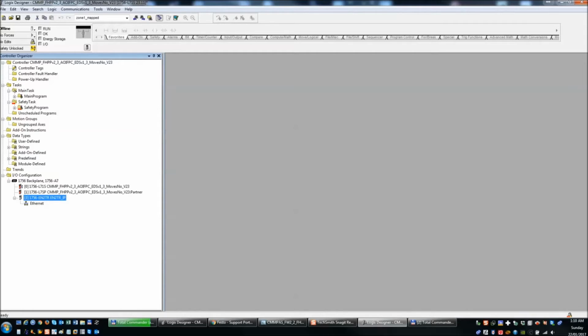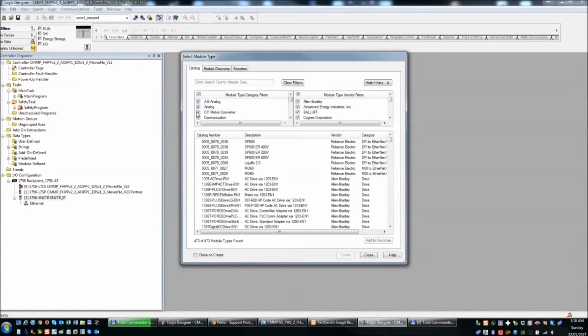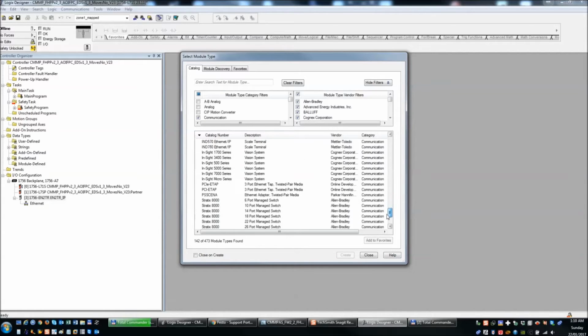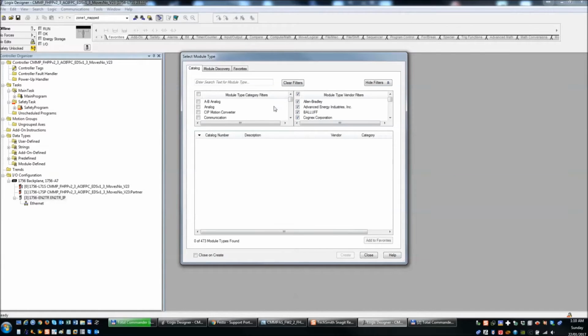The next step is to actually add the drive. Now, right-click on the Ethernet card because that's where we're adding it, and I'll try this. Ethernet, nothing there. So it's probably a Festo. I don't see it here. So let's just try CMMP. Enter. Okay, so select everything. I don't know where it is, but it's in here. And we're going to add the smallest controller, C23AM3. So we're going to hit create.